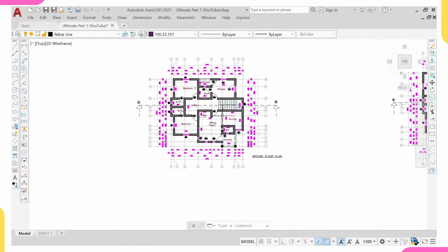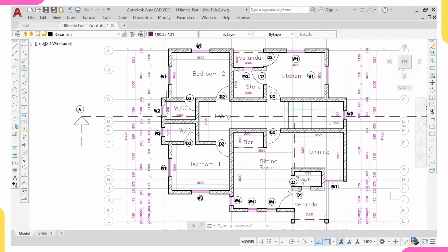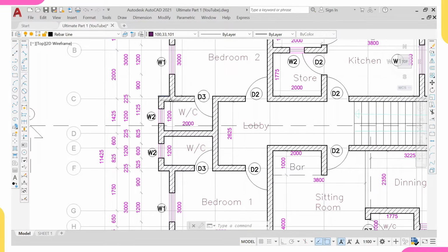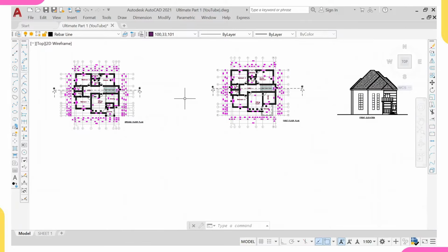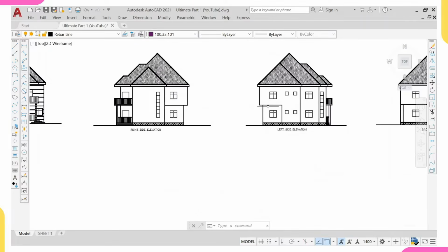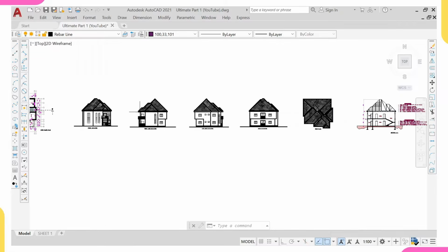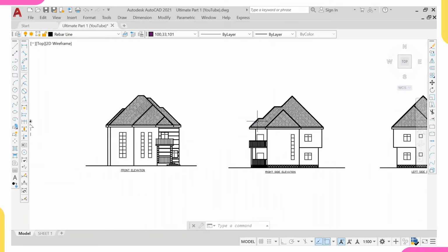Another reason why I study the architectural plan is to know whether there are cantilevers at story one. So for example, look at this. These are the toilet and bathroom. You can see there is an offset backwards. But if you go to story one, you can see it's a straight line. So it's moving straight. That means we have a cantilever at story one. This is the cantilever. This is the cantilever. So these are part of the reason why we study our architectural plan.